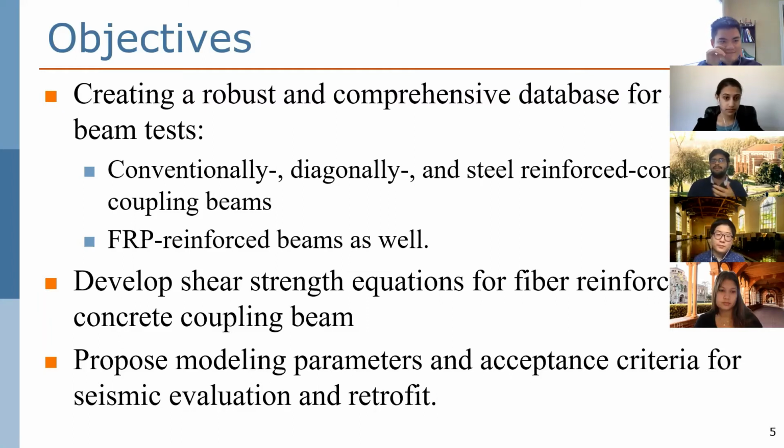So steel fiber reinforced concrete coupling beams can be used for designing in regions of high seismicity, which can provide strength and add ductility and remove the diagonal bars, which is an innovative way to save significant labor and material cost.